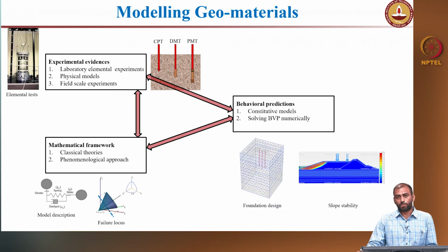So, how will you model geomaterials? That is the next important question which we need to ask: how to model the behavior of geomaterials. As you are seeing on the screen, you need to have three important frameworks. One is the experimental evidences. You perform a lot of experiments in the laboratories and understand the mechanical behavior of geomaterials, starting from as simple as a liquid limit test to a much more complex directional simple shear test. So, you have a wide variety of laboratory tests which you can carry out to try to understand the behavior.